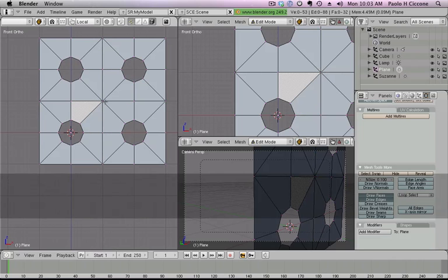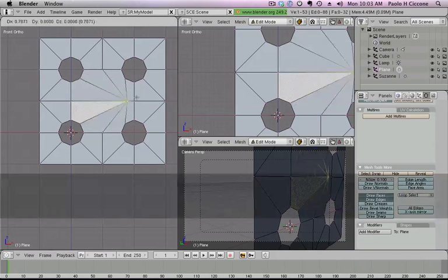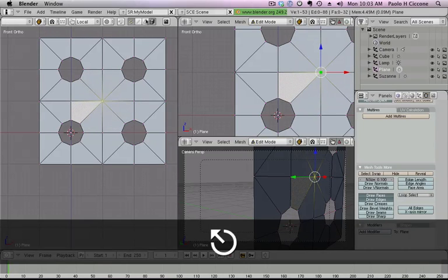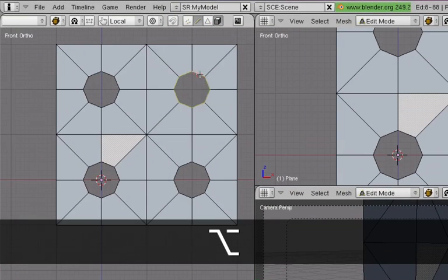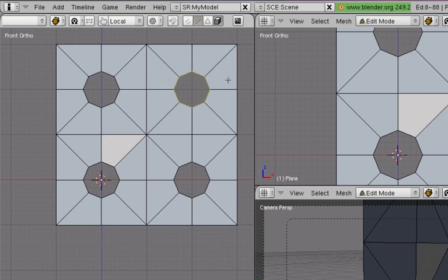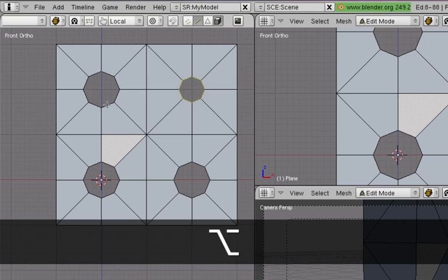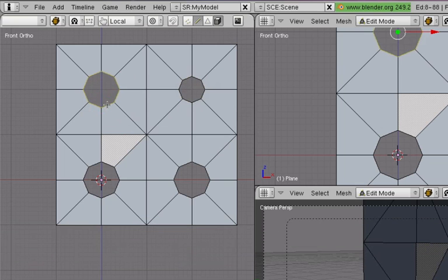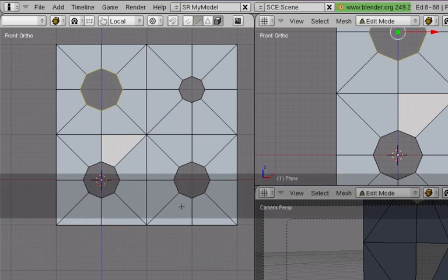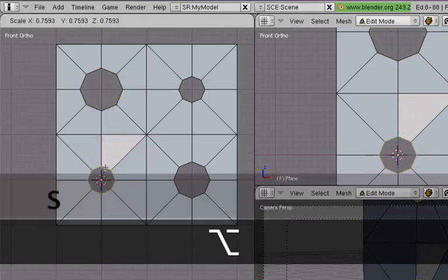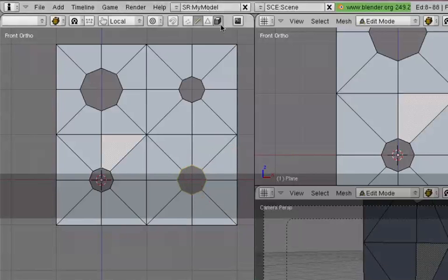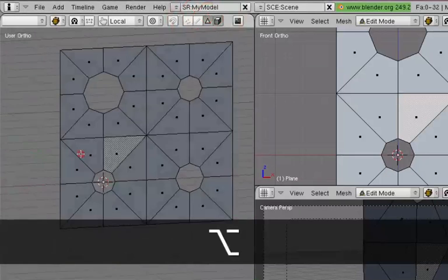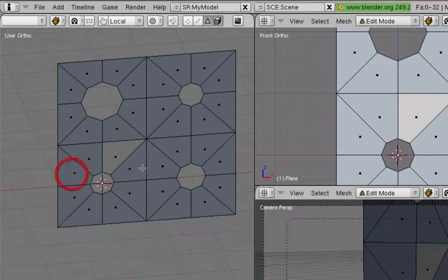And now I right-click on this vertex, and whoo, look at this. Fantastic. So now what I can do is to switch to Edge Select mode, and Alt right-click on this circle and make it smaller. And then I can right-click with an Alt on this one and make it a little larger. And I can make this smaller. And this is smaller a little bit. There you go. And now we have a panel that can work for our application.